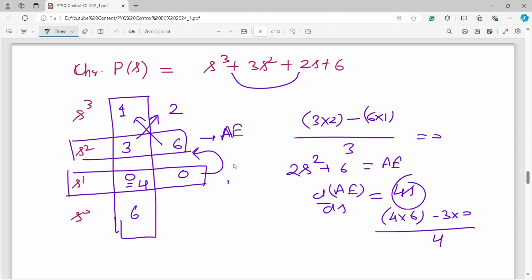Okay, so in the Routh-Hurwitz table, you can see in the first column there is no sign change. All signs are the same. So one thing is clear, there is no pole in the right hand side of the plane. But here an entire zero row exists actually.